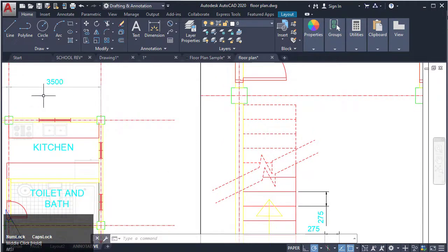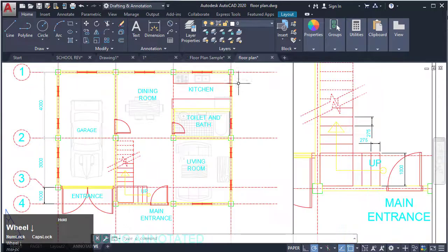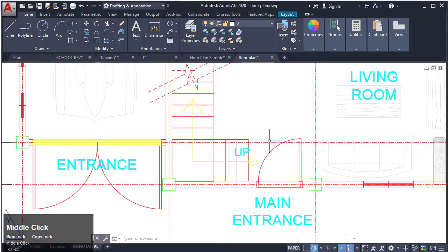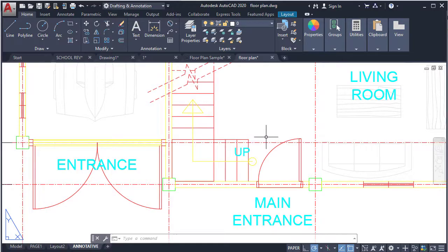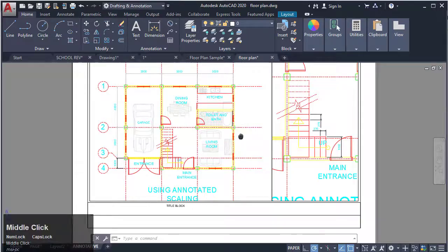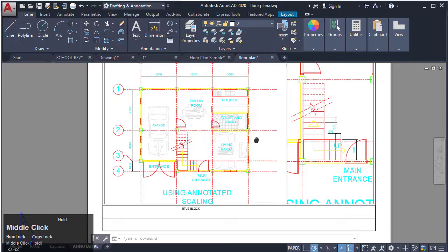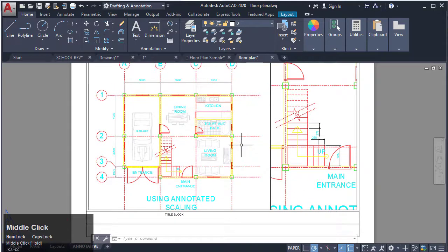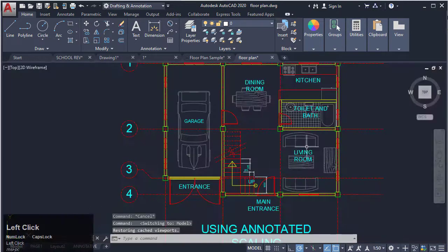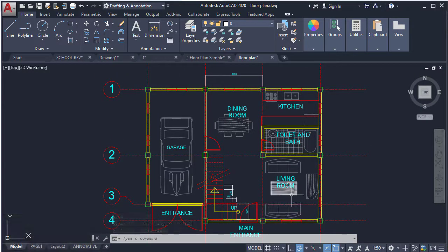The size of your dimension style is similar, even though you have two different viewport scales. However, one thing that is key here is that it is no longer visible in your 1:100 annotative viewport scale. The reason is that using annotative scaling controls the visibility of your annotative dimension. This is quite advantageous if you want to use a single drawing that is set at different viewports. So you have one drawing that has different dimensions placed in it.